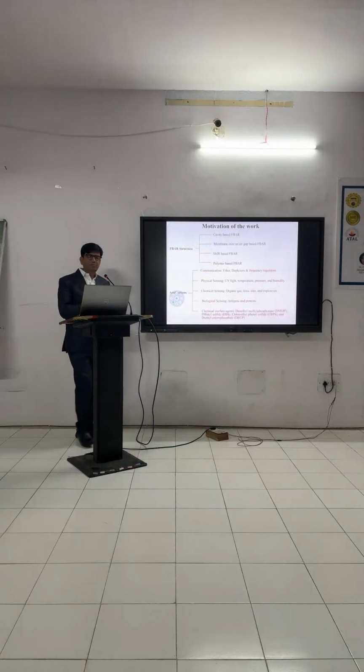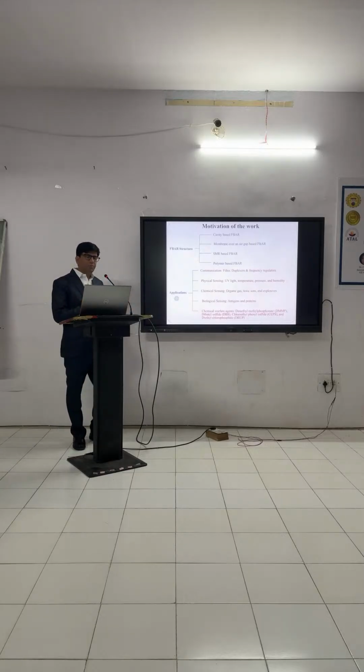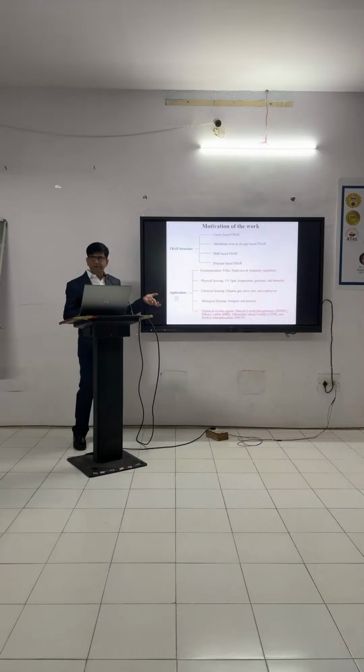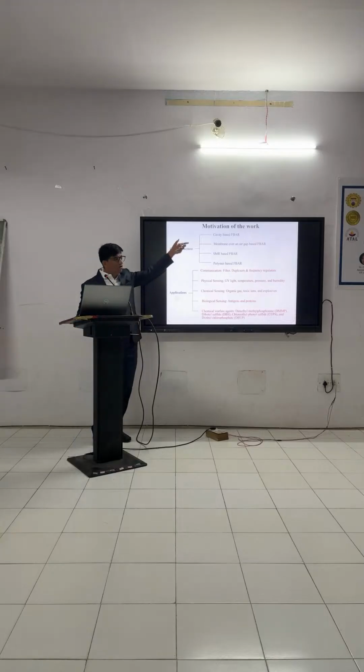So, what is the motivation towards my today's session? Whatever devices we are learning today, they can have different types of structure, which means you can think beyond that also. First we have a cavity-based FBAR, then we have a membrane-over-air-gap-based FBAR. The first one we can make with bulk micromachining, and the second one we can fabricate with the help of surface micromachining.